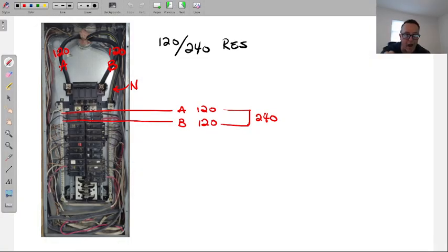All right, now we're going to talk more about why they want us to shut them off at the same time. Again, these are the things that we try to learn more about, why these things are done, but that's the main thing as we start to go into this. The hot conductors have to both be shut off at the same time. Meaning if you're looking at this, I'm going to have these breakers either together in, 2 pole A phase, B phase, or one and then one right next to it so that I can side by side join these 2 together. Or, and I don't see one on this panel, use a tandem, and again, where one breaker has 1 and 2 shut-off points. All right, these are the style breakers that we can use here.